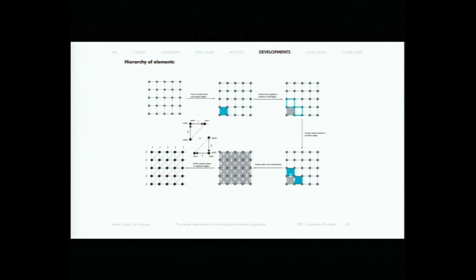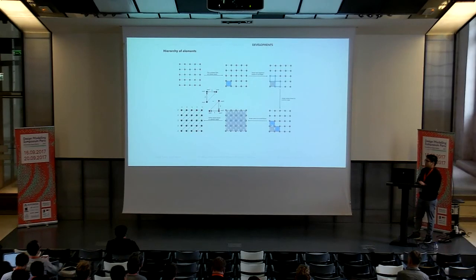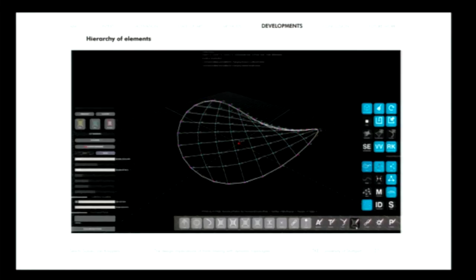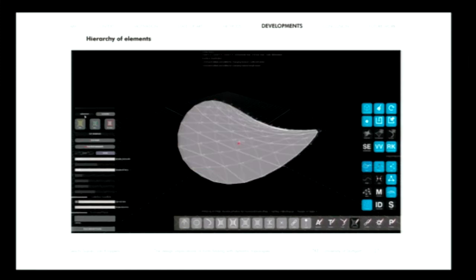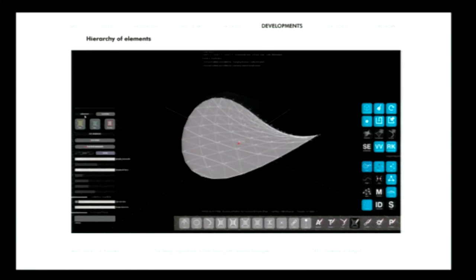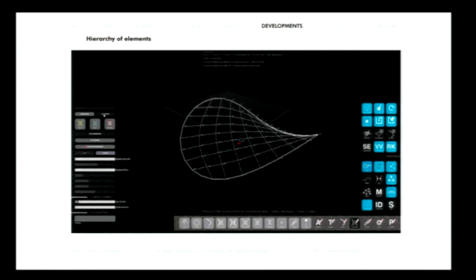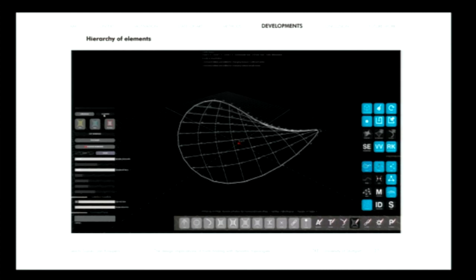All these operations occur at the level of the force topology network without explicitly altering the mesh topology network, and because of this, a reverse shift is also possible. Here is a video regarding the dynamic shift of elements, and you can see how different equilibrium conditions are created by applying this shift of elements during the form-finding process.